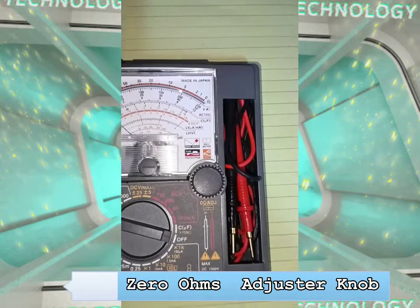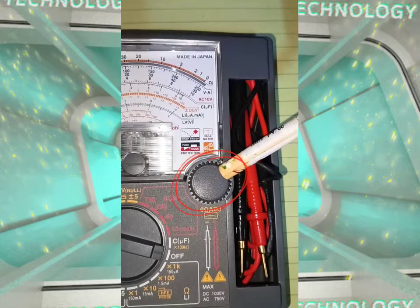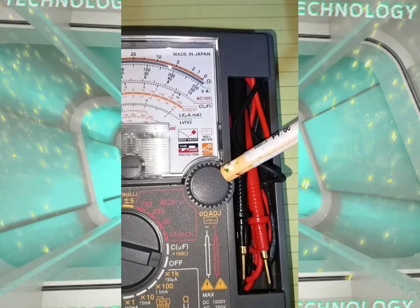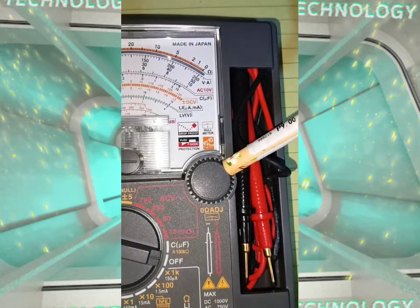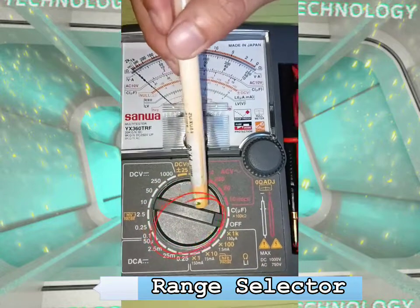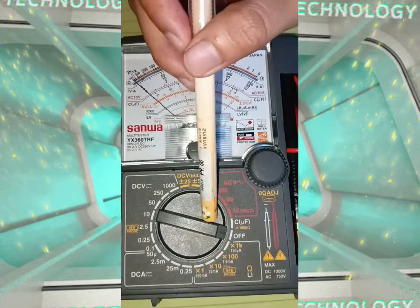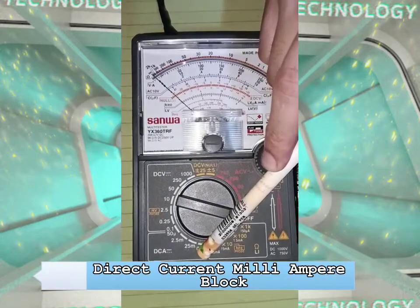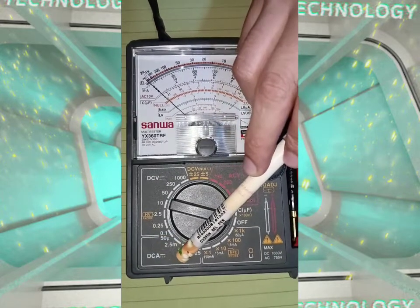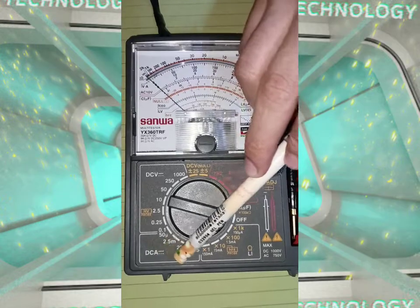The next one is the 0 ohms adjuster knob. It's the control to set the needle pointer to the zero position before and after using the multitester to attain correctness of value. Next is the range selector. It's the selector or indicator of the functions of the multitester. Next is the direct current milliampere block. From here to here, it is the block used to measure small direct current.